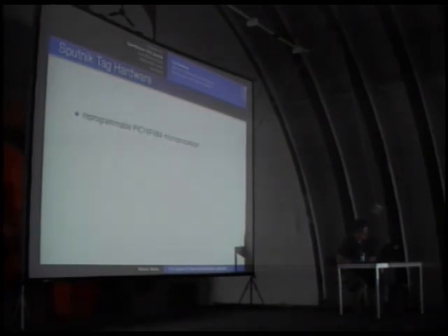Sorry. The hardware consists again from a PIC16F684 microprocessor. We mainly chose this microprocessor because it's A, cheap, B, draws virtually no power, and C, you can buy it pre-programmed, and no other manufacturer, to my knowledge, provides such services. You can buy directly from Microchip, so you don't have to pay annoying fees for distributors that are just reselling the devices. So it's in the end cheaper. But I personally also don't like PIC microcontrollers because they are not really high-level language capable.